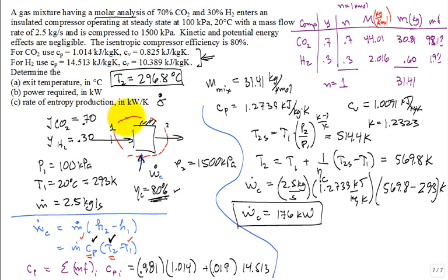Second law, control volume around the compressor. And I'm going to try and do it in this little space left, but I won't be able to do it. So it'll be something like sigma dot equal to the mass flow rate times S exit minus S inlet. There's no heat transfer. There's no entropy transfer with the work. It's steady state. Look good? Entropy balance give you that? I know the m dot. I just need to get the delta S.